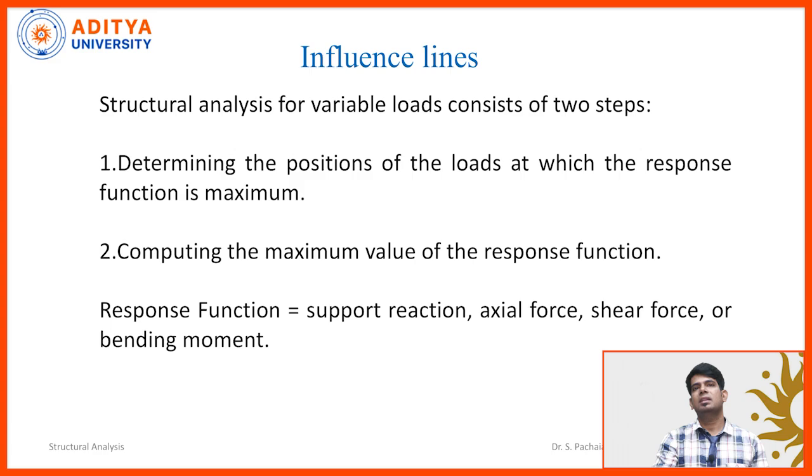So structural analysis for variable loads generally consists of two steps. The first one is determining the position of loads at which the response function is maximum. So we need to identify at which location we are getting the maximum responses. If I keep the load at which location, will I get the maximum shear force?